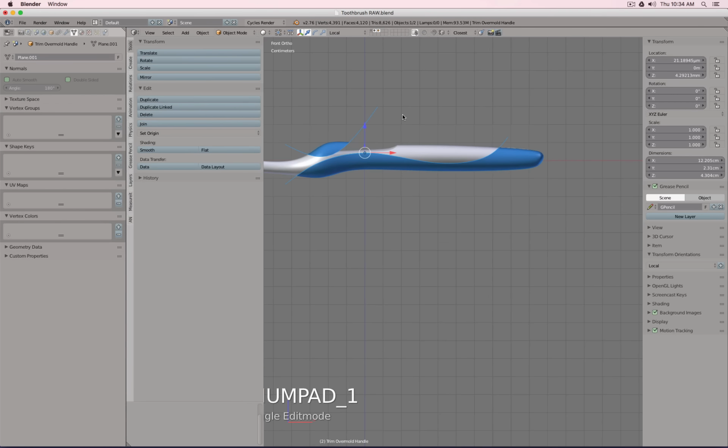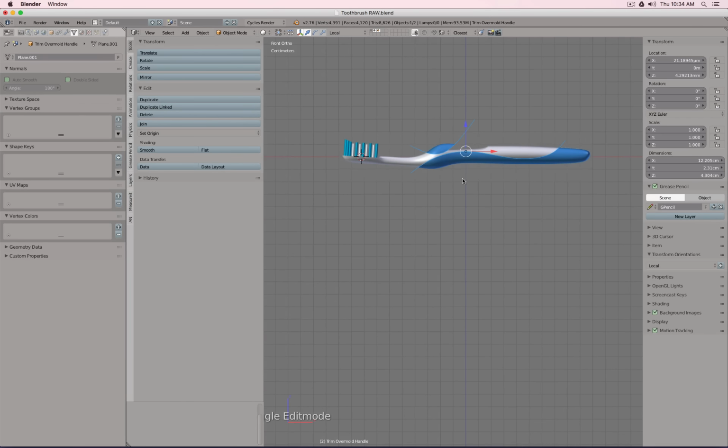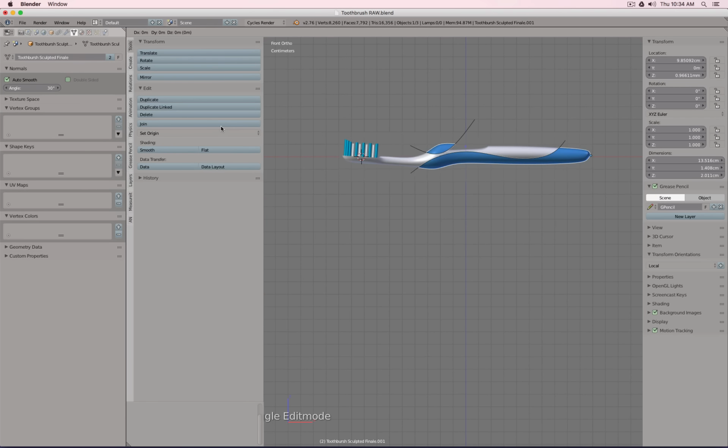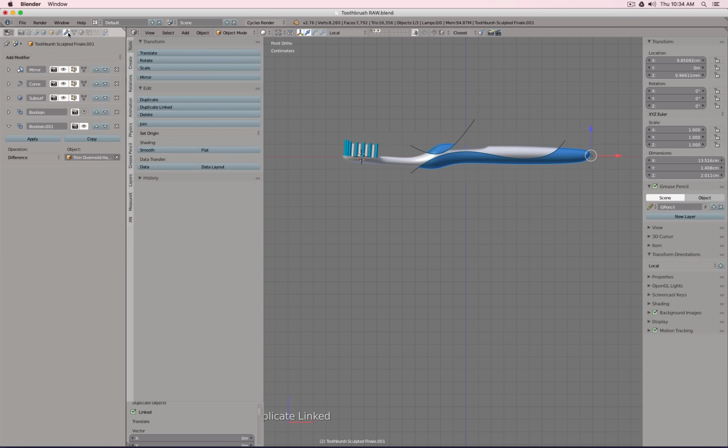So how do I do now the other part, the white one? This is now where clones come in. So I will go object and then say duplicate linked. I do not move it, so I press escape. And to get the opposite result, in this case, actually here for this one, I have to say intersect.